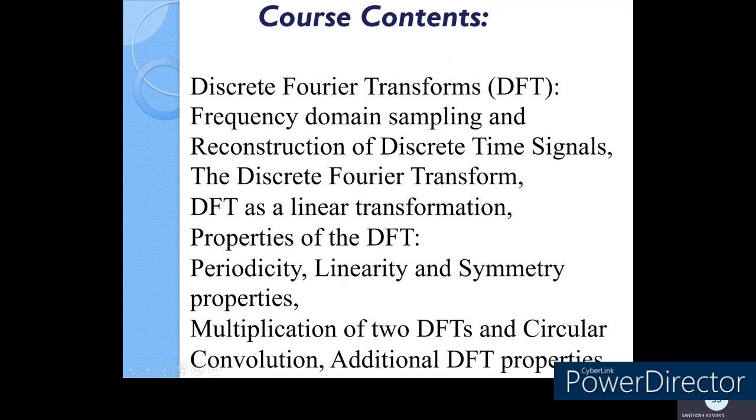And that one you are going to study as a first topic in module 1, where we are going to consider the DTFT of the non-periodic signal, and for that you're going to perform the frequency domain sampling in order to obtain the formula for the discrete Fourier transform. Later we'll do the reconstruction of the signal. That is, once we find the discrete Fourier transform, we need to find the inverse discrete Fourier transform. So that you're going to look into as the first topic in module 1.